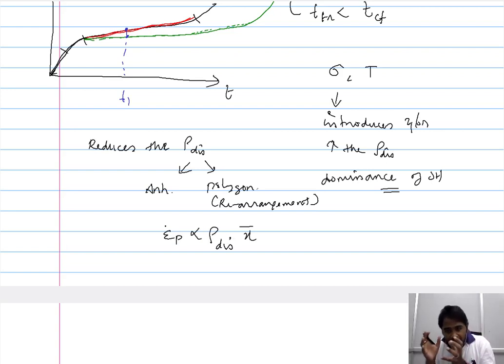However, when you move into the steady state condition, the amount of dislocation density is significantly reduced, and therefore the number of dislocations that contribute to the plastic deformation is reduced, and therefore you see a decreased creep rate in the steady state condition.